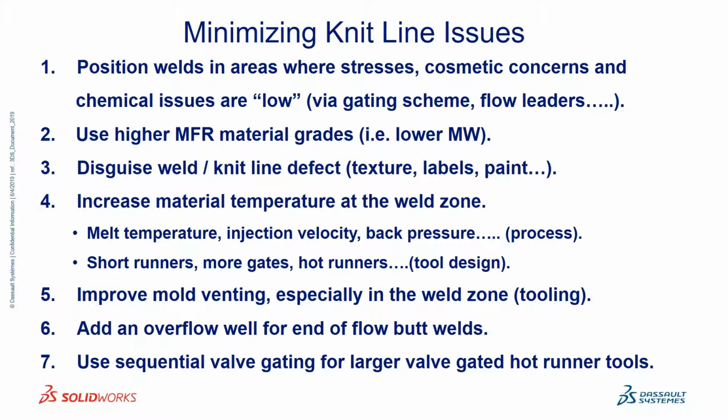Keeping things hot, again, as a process variable, we said mold venting, I can't stress enough, is critical. Not just at the weld zone. Mold venting is extremely important just in terms of being able to fill the mold faster. The more venting you have, the faster you can fill. And especially you need venting in the areas where the welds are to cut down on the size of the V-notch, avoid possible gas traps, and so on. Again, keeping the welds along the parting line, as Ramesh showed, is the best location, because that's the easiest place to vent. In extreme cases, you can use overflow welds, which I'll show an example of.